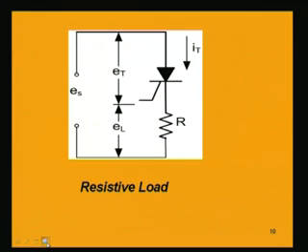That means, we want to supply an AC power to a load not for the whole input cycle of the input voltage, but for a limited portion. So, typically one circuit demonstrating the phase control using thyristor is shown here, and we are taking a resistive load in the beginning for simplicity. So, we will be understanding how the phase control is being achieved using resistive load and then we will also be discussing about an inductive load.